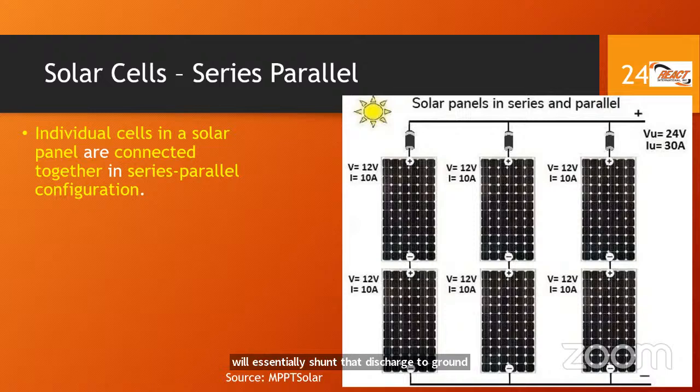should it, similar to what you will have protecting your equipment in your house, where you have surge arresters that's comprised of metal oxide varistors or MOVs. It will shunt that spike or transient to ground. You have equipment that will do a similar thing for lightning.